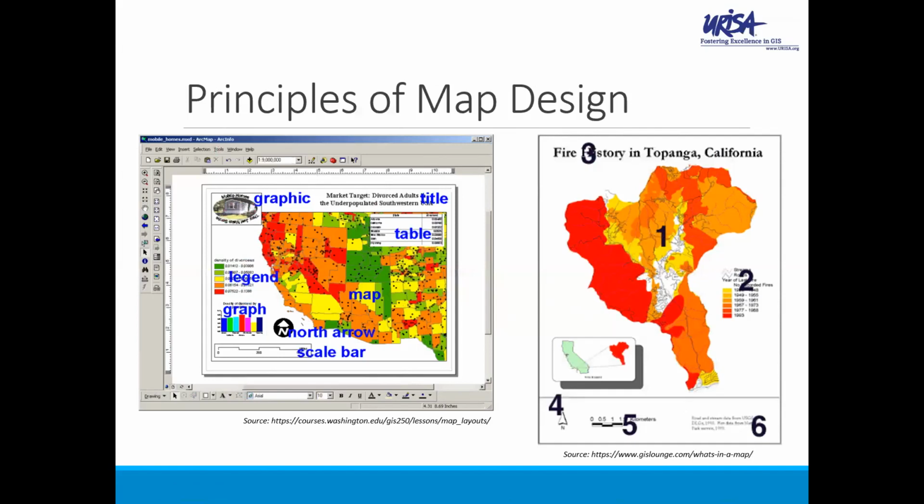Are you providing the accuracy and error? Is it represented? How is it best represented on your map? What about the scale? There is a difference between size versus scale and how that affects map design. Do you have a scale bar? Is the generalization of large scale versus small scale most appropriate for the data you're trying to represent?